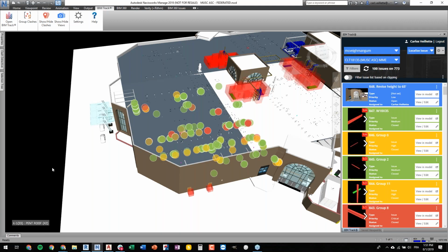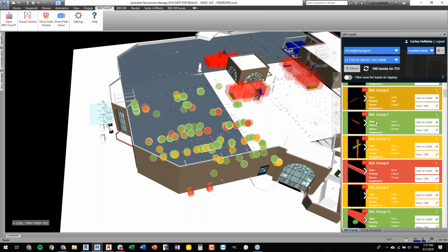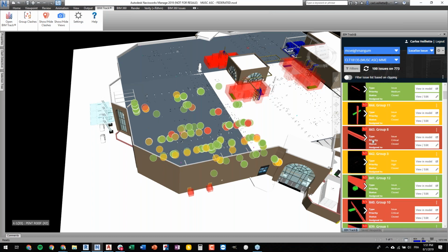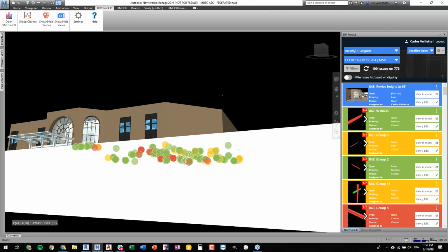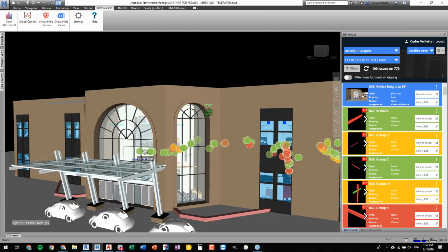Yep. So in terms of, I believe you guys see my screen right now. Can indeed. All right. So just to answer the question, this is what the BIMTrack add-in looks like within the Navisworks environment. So we've got different ways to transfer issues from Navisworks to the cloud and then retrieve them in other softwares. We've got the clash to issue feature, which was used on the project here to batch transfer different clash tests. We've got save views to issues, and we've got different options in here to just raise issues on the fly as you navigate the model and do some constructability reviews or design review.